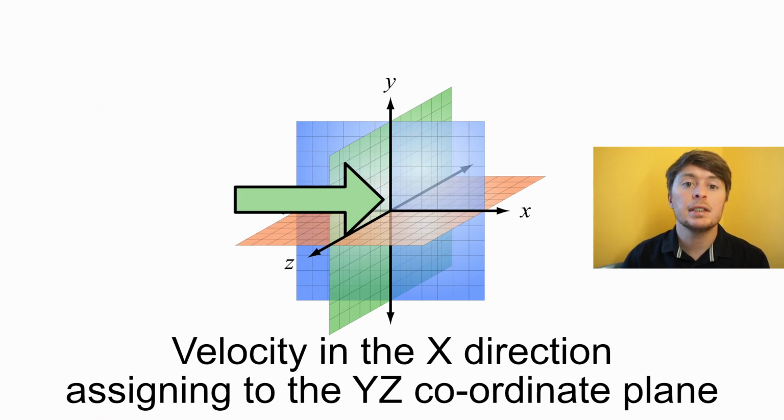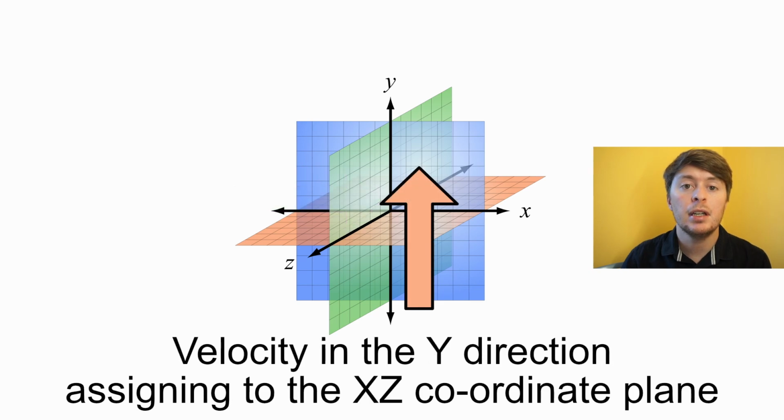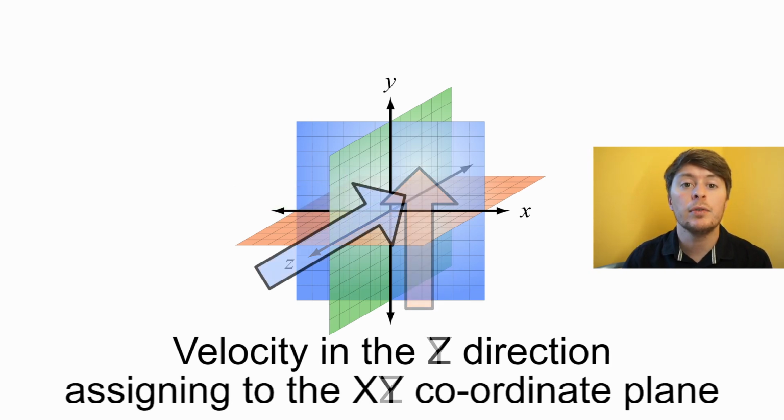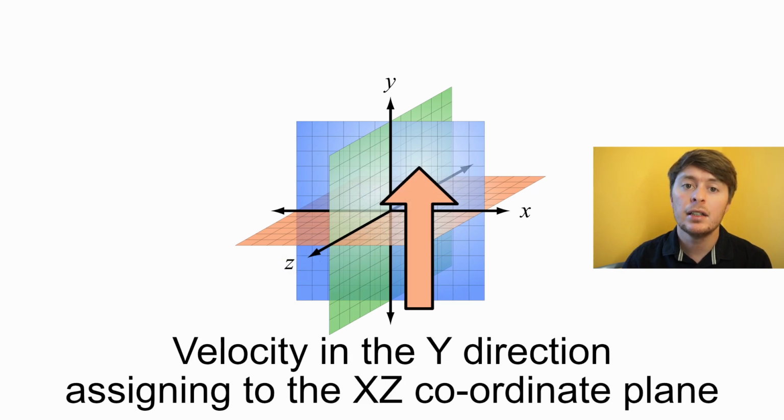And now this is important to define which orientation and which axes we want to use for our coordinate system to assign our velocity values onto. In this case, it's set to 1, and 1 is for the XZ. So we're using the X and Z coordinates to calculate our Y velocity values.